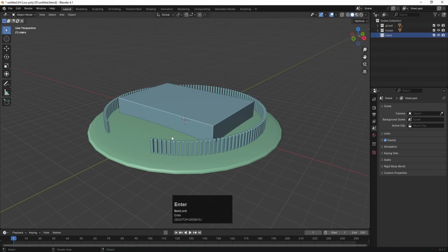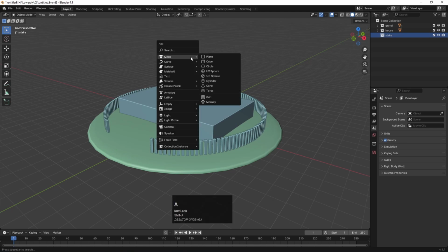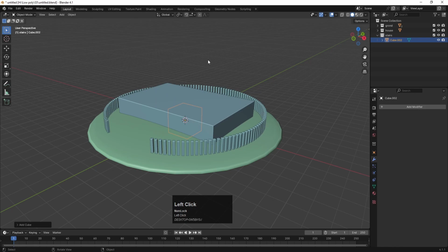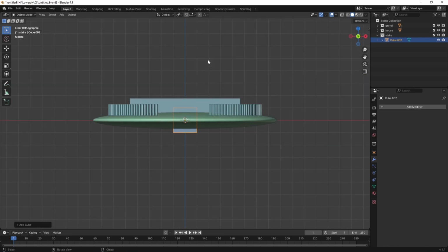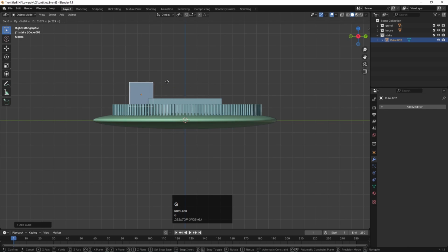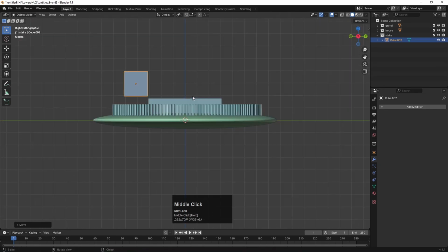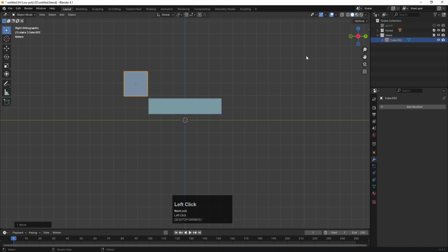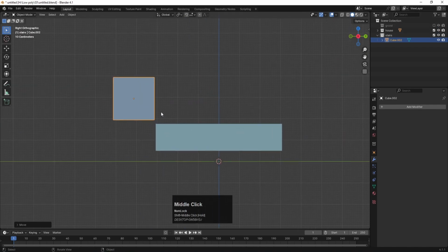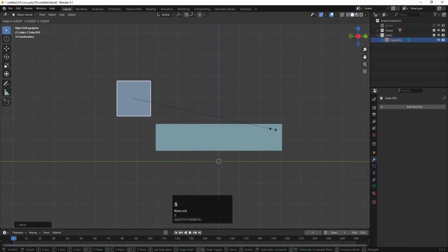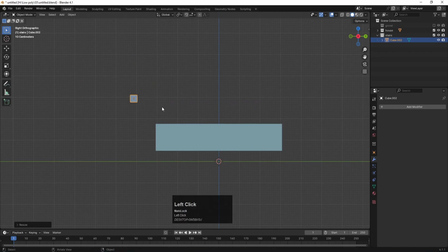Now we will create our stairs, so let's try to do that. I'm going to press Shift A, choose mesh and choose cube. I'll go to the front view, or let's say from this view, press G and let's try to move this over here. You can see over here like that. Then press 3 and let's hide this ground for now because I need to focus on this one. Then press S for scaling and scale it somewhere around like this.